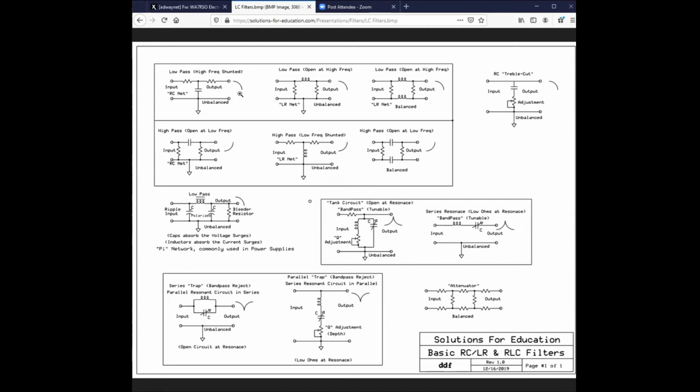All right. Now, in that same respect, here was one that people have used years ago, when you had a turntable with a 78 RPM player, or record rather, and it had noise, scratches, if you will. Well, you could take this guy here, and by adjusting the resistor, you could determine how much this capacitor shorts out the hiss on the record.